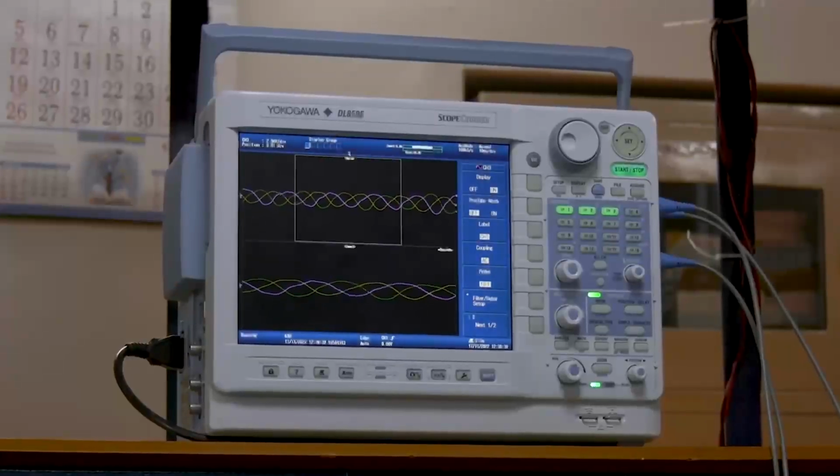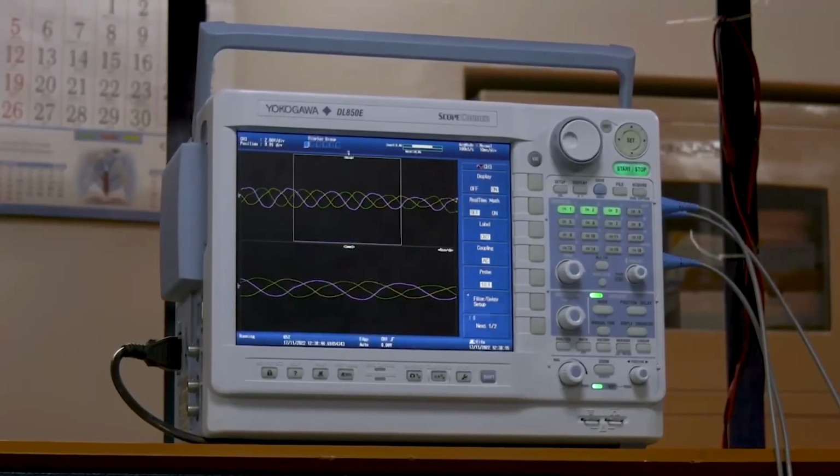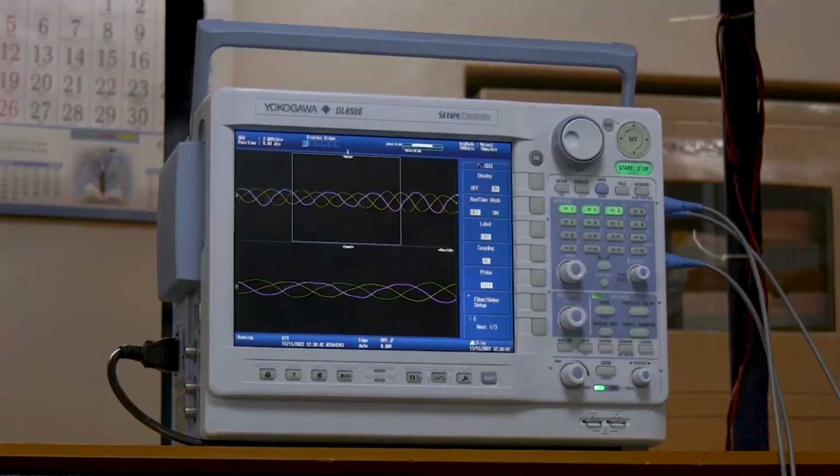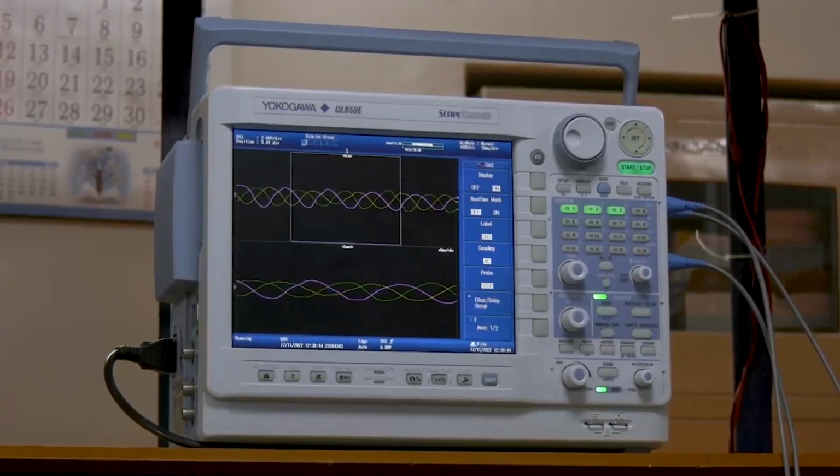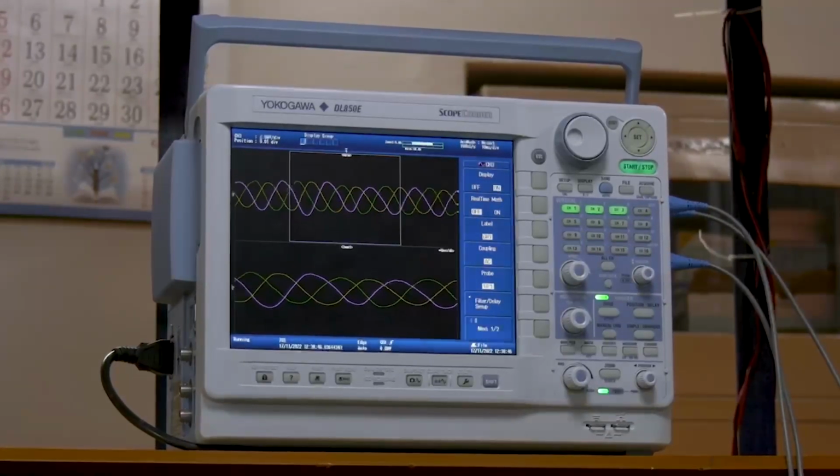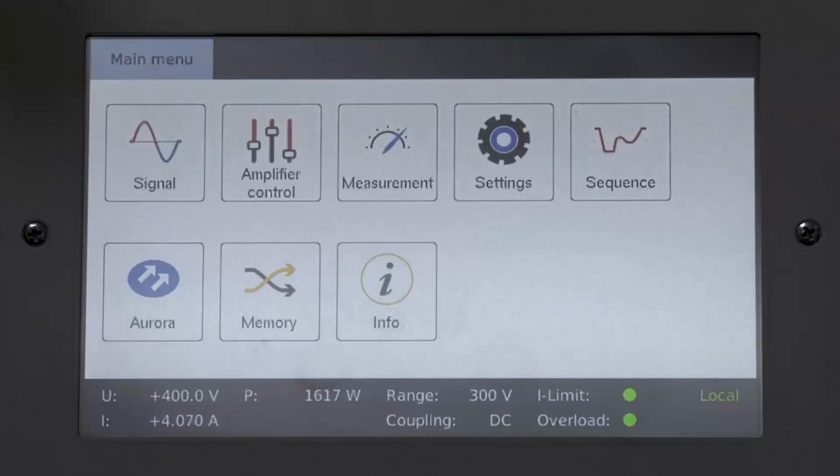By looking at the DSO, we can clearly witness that the decrease in DC load increases the current magnitude. Looking at the power amplifier power sign, which is positive, means the power is flowing from the DC bus to the AC grid.